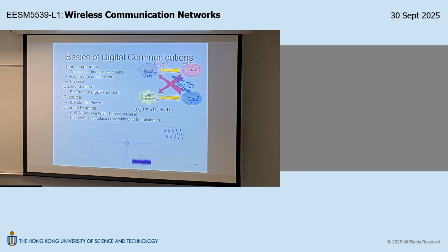You just think about the exercise, right? Let's say you are asked to put 16 points on a constellation, on a two-dimensional space. Now, in this way, how many freedom do you have to put the 16 points? Each point is living in a two-dimensional space, right? So the coordinate of each point is 2 coordinates. If you look at the polar coordinate, r theta, each point has r and theta being different from each other. So using this design, you have 2 freedom to put 16 points on a two-dimensional space under this energy constraint.